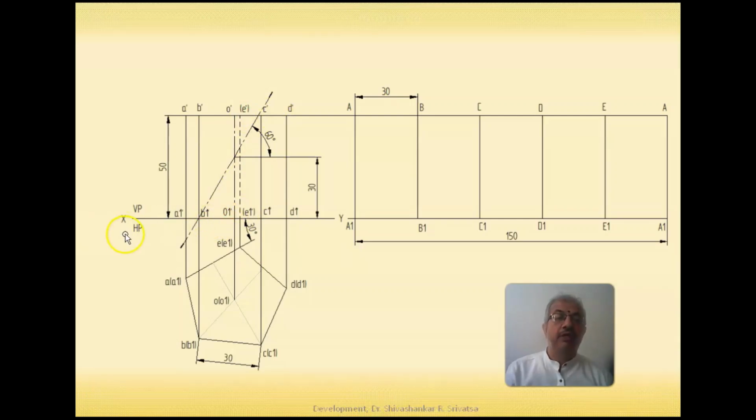So we will have to identify those points. Now I'll just represent them in an order starting from the base here, and I move clockwise or move from the front and go then towards the back. So I'll represent these points both in the front view as well as the top view. This is how we represent the points.